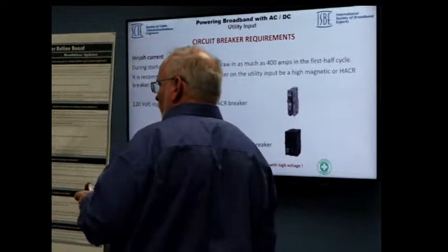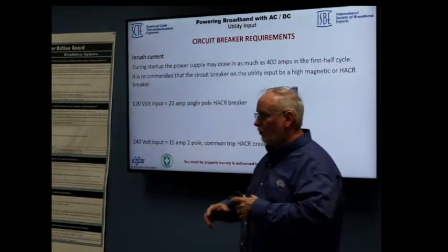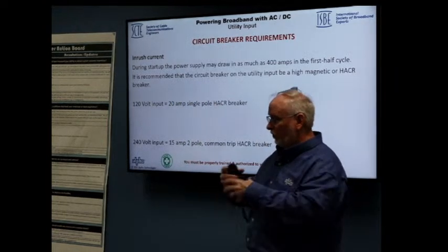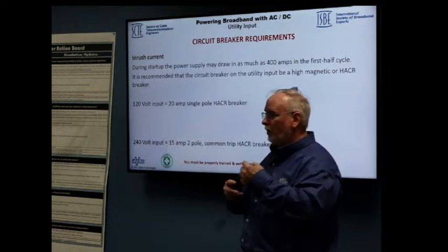You cannot put a standard circuit breaker to drive one of these. We have a very high inrush current. You have to charge a tank circuit. It's a 60 hertz tank circuit. It's why we call it a ferro. A ferro runs a tuned circuit.